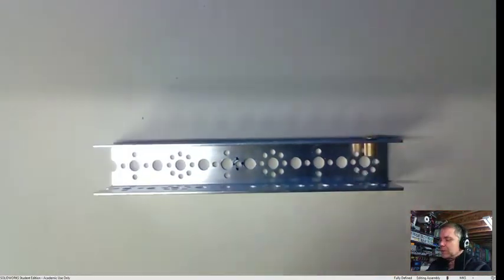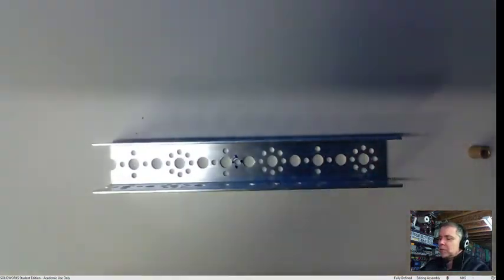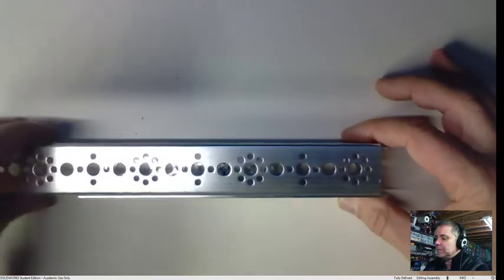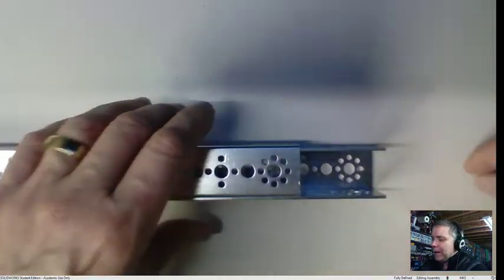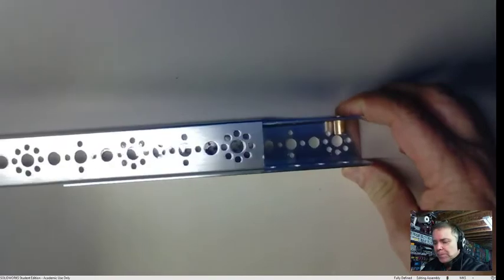Now, to do that, we have to come up with a way of creating a rotary to linear actuator. And a simple way to do it is like this. This is how I'm going to do it in this demonstration. We'll just get a single channel like this. Take that bushing out. A single channel like this. We'll put another channel inverted on top of it like that. And we're going to have it slide in and out like that. Okay, that's all we're going to do. We'll put a little stop on this side right here. Just use a bushing. Goes in there, so when it slides it bumps into the bushing.